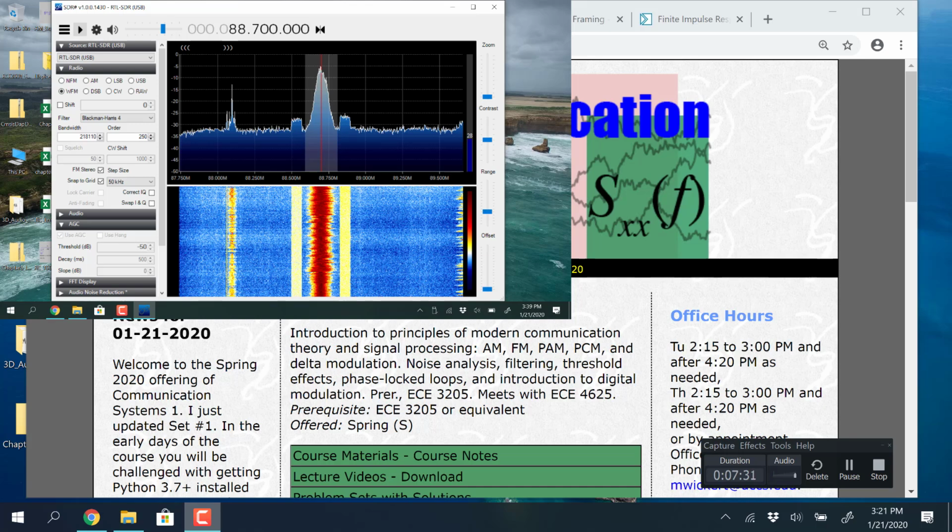You're bringing up a good point, though. There is noise. There's always noise in a receiver front end because the signal is weak. I'd be willing to bet that, well, maybe not. It goes through the walls. FM is short enough wavelength that it goes through the studs. They're far enough apart. But that X is a pretty good screen.